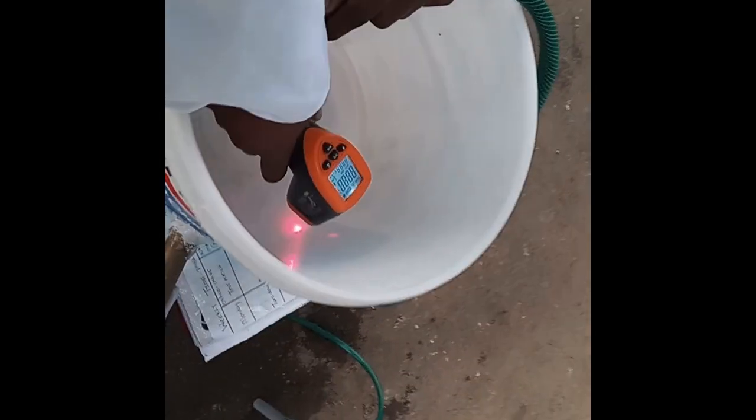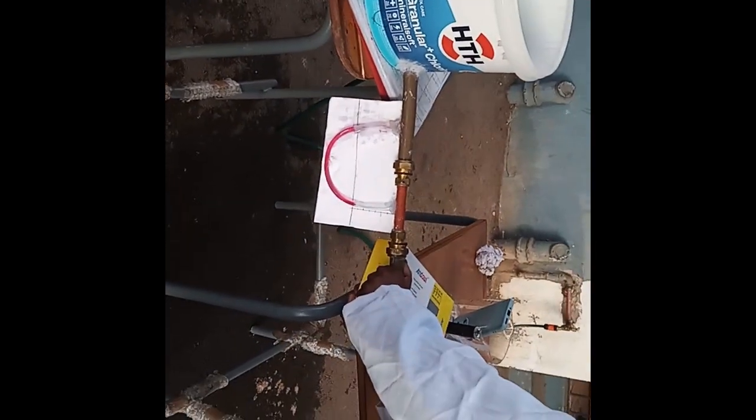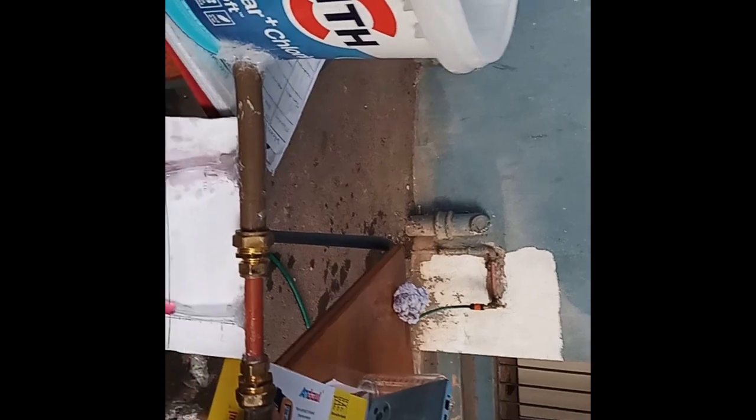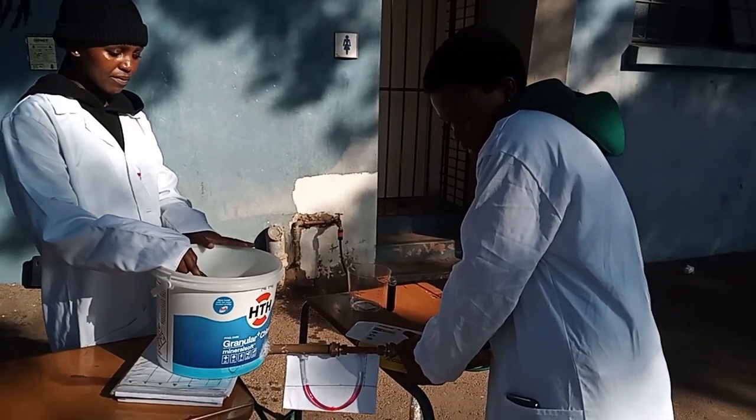As we were filling the water inside the bucket, we had to make sure that the open end of the pipe was closed to ensure that the water does not flow out as we're trying to fill up the bucket. Once the water had reached a certain level in the bucket, we then allowed the water to flow out of the pipe. We let the water free flow for a short period of time to make sure that we get a steady flow and that the flow rate coming into the system is the same as the one going out of it. Once the pressure begins to change, you will then note the change in height in the manometer fluid.